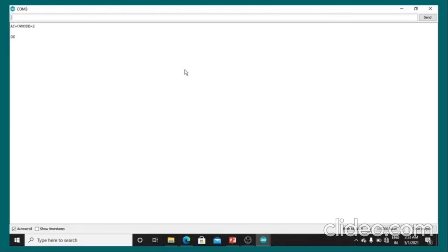Yeah, so our ESP is set to mode 2, and in case we want to check what our Wi-Fi password or hotspot password is, let us do that by AT+CWSAP. Let us do that. Okay, it says error, we have done something wrong. Okay, so we have to also put the question mark here. Let's try that way. Okay, yeah, so there is no password, as you can see here, and the name of this device is ESP_928369.